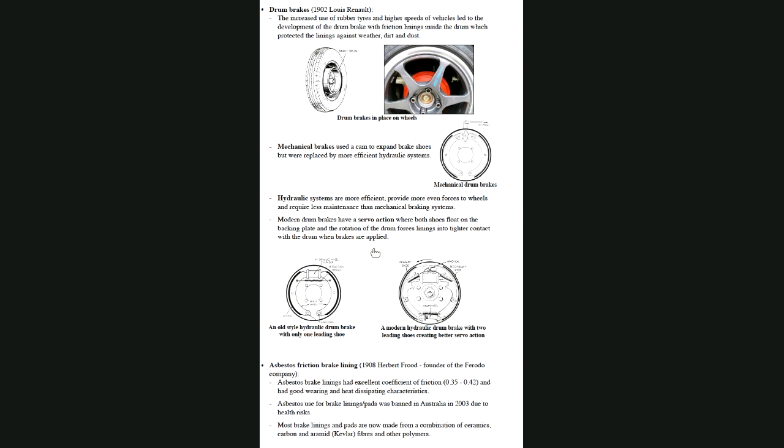And so this is the old style hydraulic brakes. You had a hydraulic cylinder there, and all it did, and these were connected to the backing plate so they wouldn't slide. And all it did when you put your foot on the brake, it pushes a piston out and pushes the brake lining up against the brake drum. But this is the latest thing with brake drums. Like these Hyundais would have this servoing effect.